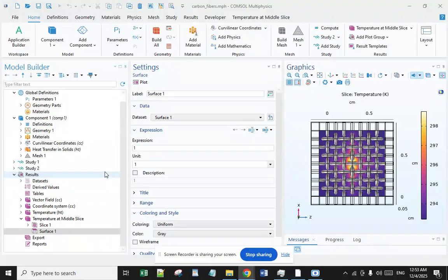C_p is the specific heat capacity of the fabric measured from the DSC experiment. h is the heat transfer coefficient between the fabric and the air, and l is the boundary layer length of this heat transfer due to natural convection.